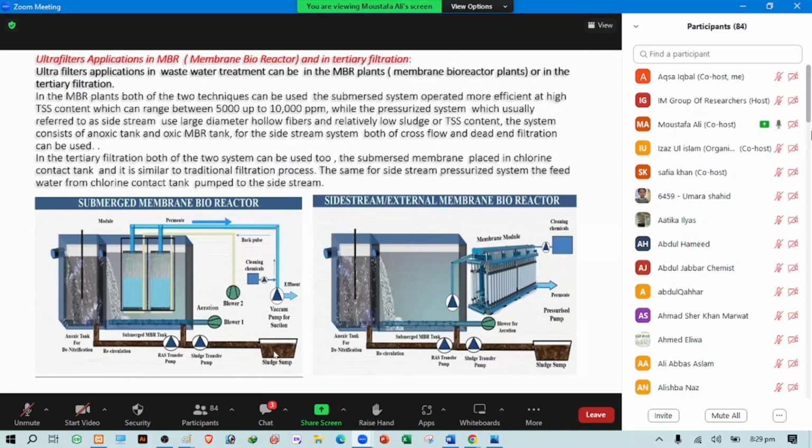So we have continuous thickening of the activated sludge in this process. Meanwhile, at the same time, we also have to pump the sludge back to the anoxic tank when it starts to increase in volume, for further degradation process.